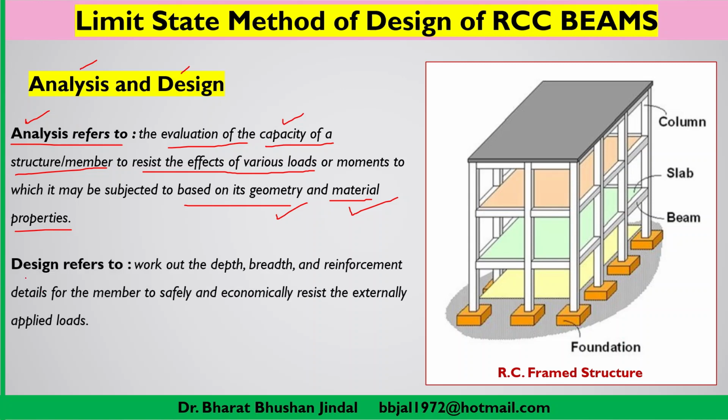Now let us briefly discuss the meaning of design, so that we should never get confused about the meaning of design. Design means working out the depth, breadth, etc. That means working out the dimensions of the cross section of the member, and the reinforcement details which we are going to use in case of an RCC structure, so that the member can safely and economically resist the externally applied load.